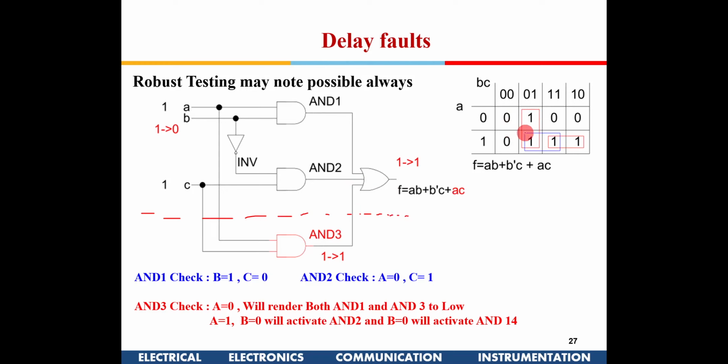Suppose I have to implement this particular function. Just take these two and these two, AB plus BC, only this much portion of the circuit with a 2 input OR gate. Is it the same function? You learnt about K maps, right? When we do K maps, this one can be clubbed like this, which is shown as red. This also can be clubbed like this, right? So if I do just this much also, this function can be realized, right?